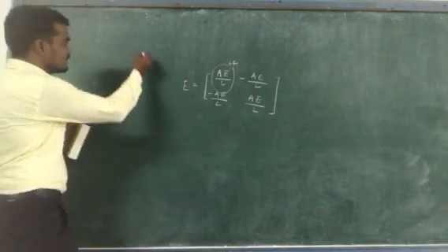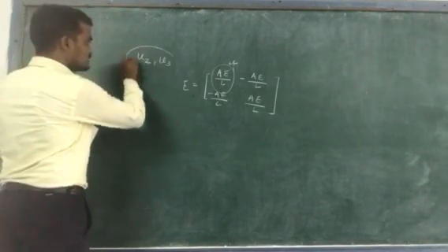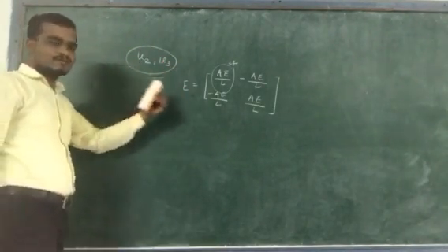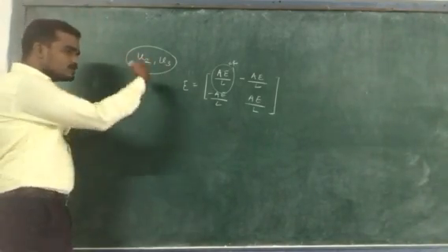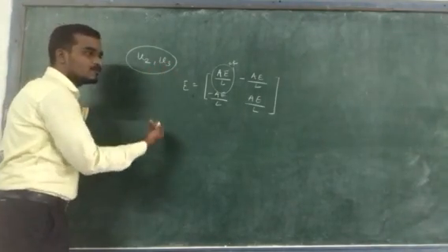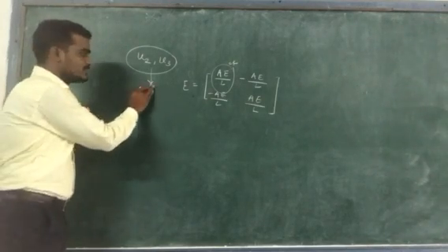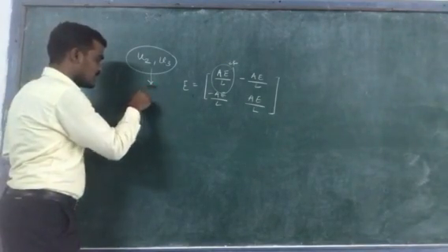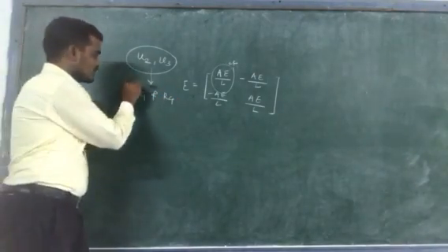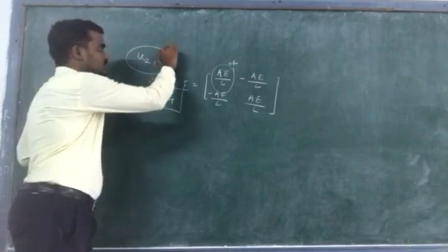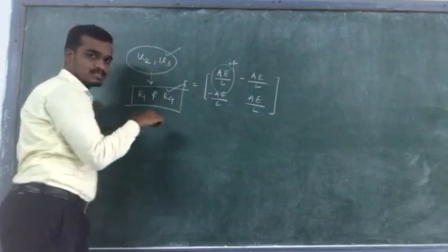So you will get the displacement values, for example U2 and U3. These are the unknown displacements. You will get these values first by applying such a procedure. Then, by using these displacement values and the force equations, you will get the reactions or forces, meaning the support reactions, for example R1 and R2 if a 4 node system is there. First you will get the displacements, then the reactions or forces at the supports.